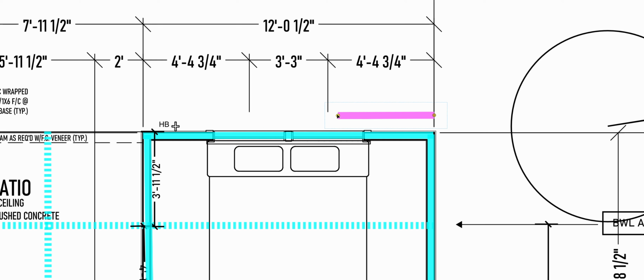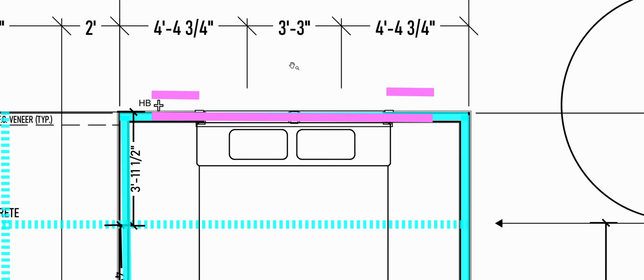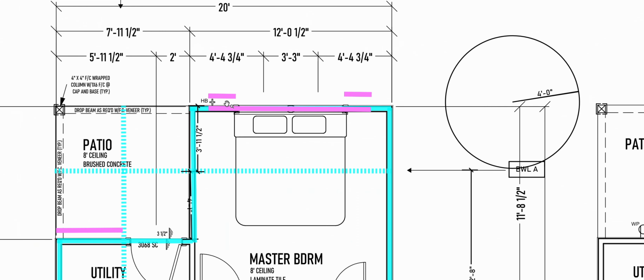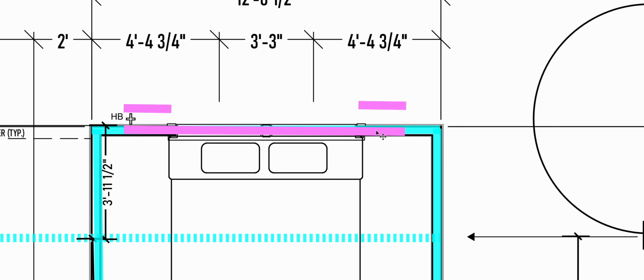And the portal is basically going to look something like this, where I have a short sheet of sheathing on both sides, and my header in the window is actually going to extend over those so that they overlap, right? And it's going to get nailed on. And it means that that header now has to be a minimum of 2-ply 2x12 in order to get enough strength area for the portal. So the original framing plan might have said I can use 2x6s here, but now if I have a portal, I can't do that. I have to use a 2x12. All right, it's all in the rules.